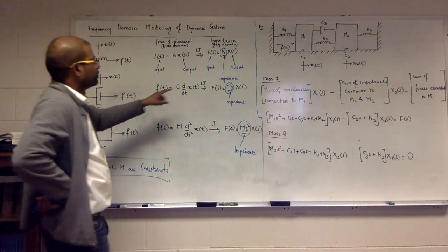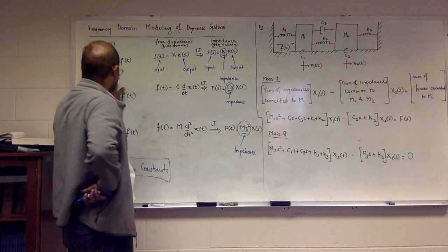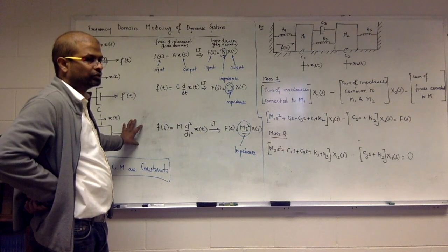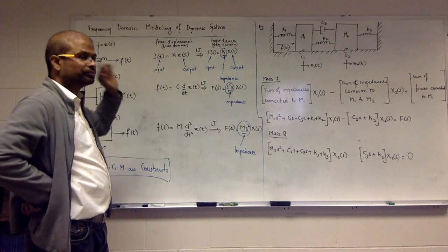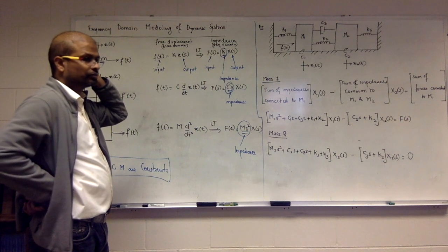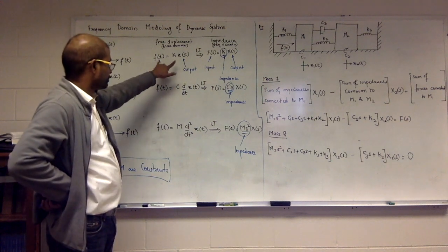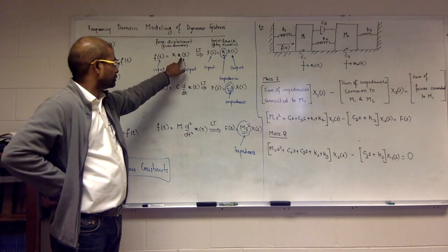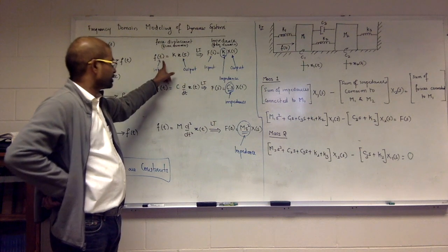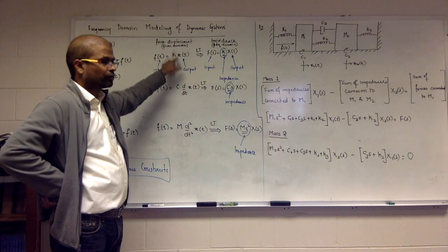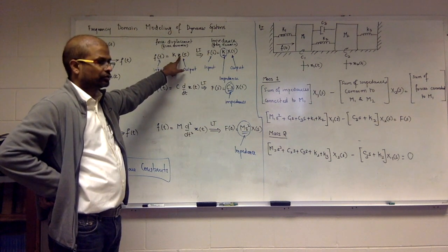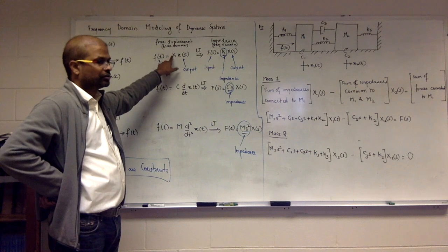So these are the basic building blocks: spring, damper, mass. What does impedance mean here? It's just the Laplace equivalent, like a big constant. It's the input-output relationship. You see, this is input and this is output. So K is the input-output relationship. The force you can say is proportional to displacement, and the proportionality sign is replaced by K, where force is input and displacement is output.